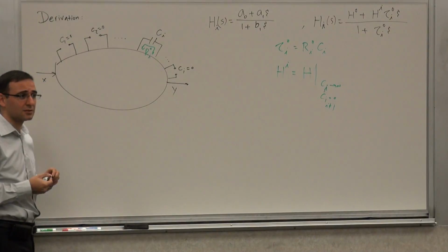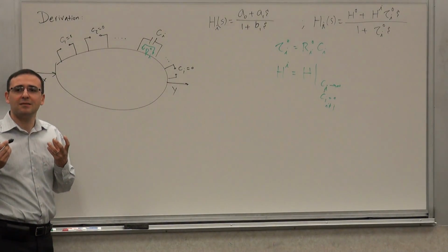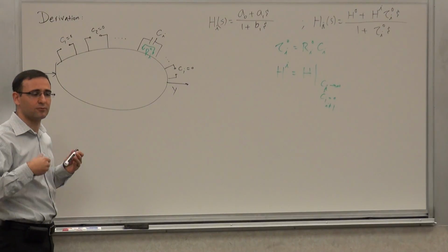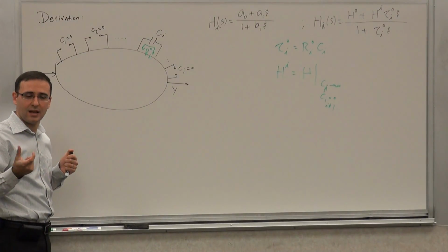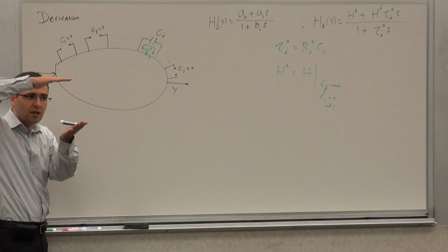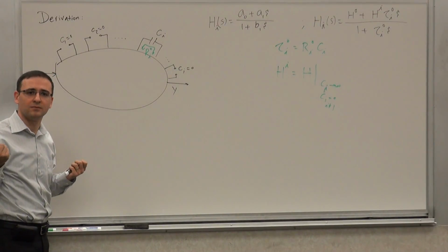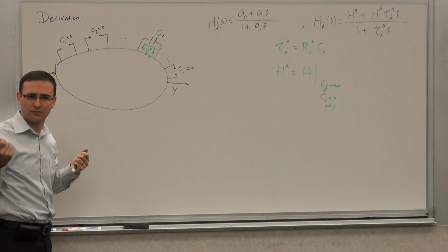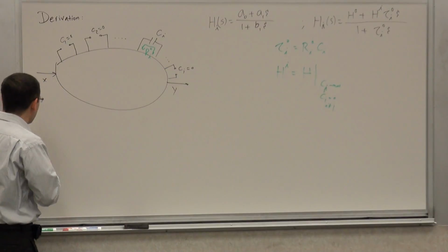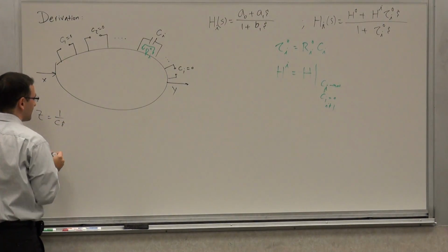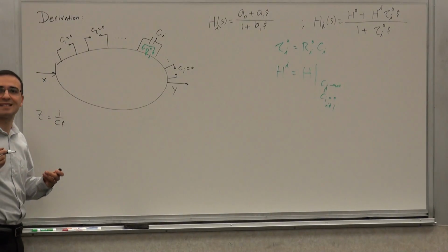Let's say I have only capacitors. How can I get the transfer function for a system with a finite number of elements, lumped elements, written in a ratio of 2 polynomials in S, right? How do you get S? Where does S come from? The S comes from the capacitors, right? The only thing that can introduce a frequency-dependent element. So an impedance or admittance, the impedance of the capacitor is 1 over Cs. So every time I have a C, I have an S.